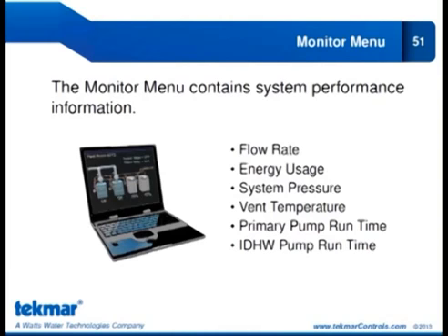The nice thing about the 28402 is that we want to make sure it's very easy to connect to, and from a contractor standpoint, they don't require any extra parts such as a power supply. The control provides power and takes a feedback signal from the flow meter. So that's the first thing.